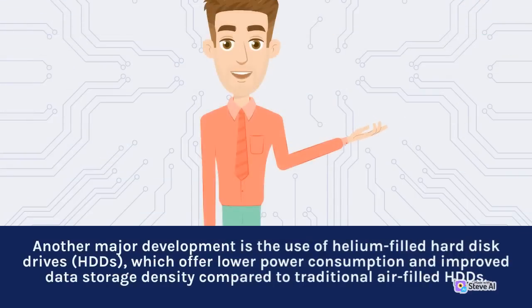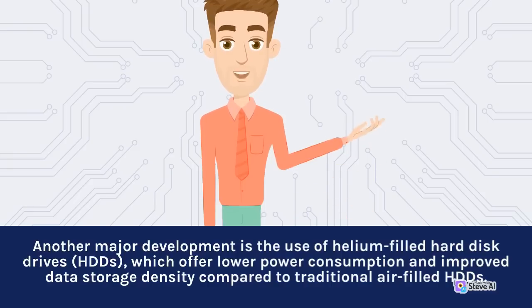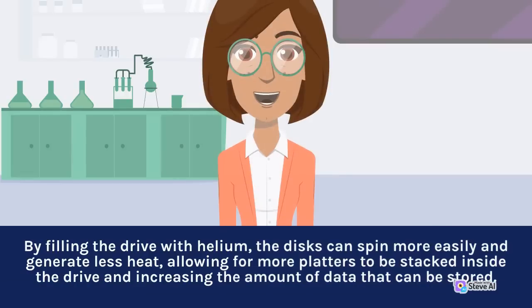Another major development is the use of helium-filled hard disk drives, HDDs, which offer lower power consumption and improved data storage density compared to traditional air-filled HDDs. By filling the drive with helium, the disks can spin more easily and generate less heat, allowing for more platters to be stacked inside the drive and increasing the amount of data that can be stored.